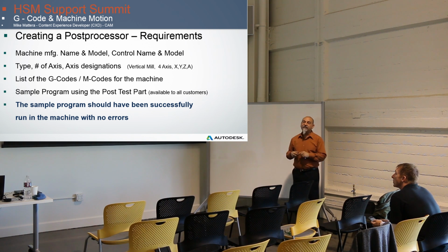That can be enough. For some of the more sophisticated machines, when you start getting into 5, 6-axis lathes and multi-spindles and part swapping and all that kind of stuff, the person writing the post may actually need the programming manual, because there are other levels of complexity to the code that he might only be able to get out of the manual. But for most simple 3-axis machines, that's good enough.